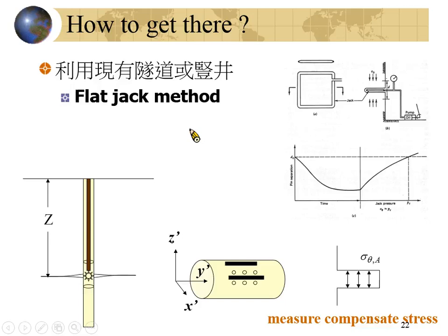So you can try to make the geological mapping during the drilling. And you will have the benefit if you have a small tunnel beneath the main tunnel. Then this small tunnel could be the drainage path for the groundwater table. So you will have fewer groundwater related problems. The other benefit: this small tunnel can be used for the maintenance of the main tunnel after the tunnel is complete. So there are several usages for the advanced tunnel.